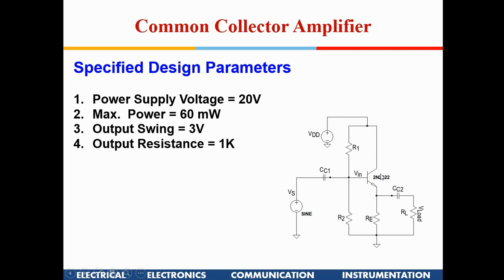Okay, so similarly in the transistor, the voltage across the transistor would be again close to 10 volt, because 10 volt you have dropped here. And what is the static current which is going to flow here? It is again going to be 3 milliampere. So around 30 milliwatt of power will be constantly dissipated here.